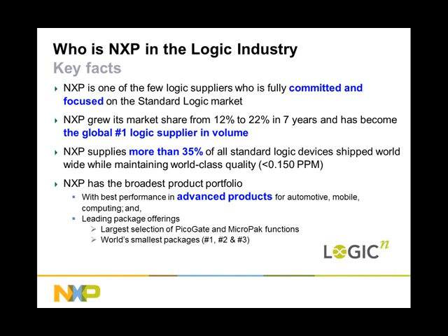For example, we introduced the GS package, which is a 0.35 pitch, 4 years ago. Then we introduced the GN package, which is a 0.3 pitch, 1x1. And just last year, we introduced a diamond package, which was 0.8 by 0.8. However, it has a 0.5 pitch. This is the one that I mentioned earlier that reduces your assembly cost.